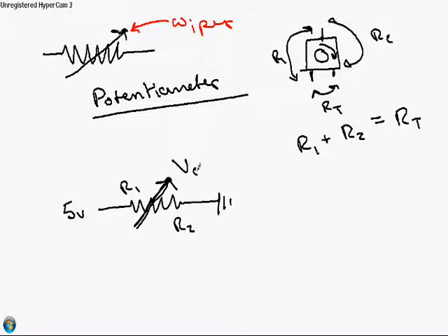And so this is your V out, and it's the ratio, depending on how much that dial is turned, between these two things. So this is useful. Again, you can just use one side of the device. You can just flow from here to here to vary the current, or you can go from here to here, or you can use the whole device to get a voltage divider to set up a reference voltage.